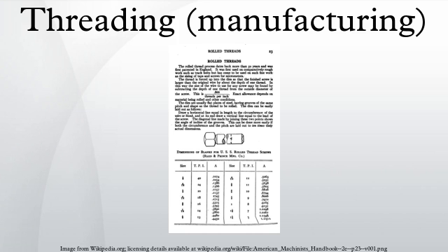Another variant of form milling involves holding the cutter's axis orthogonally and feeding the cutter in a toolpath that will generate the thread. The part is usually a stationary workpiece, such as a boss on a valve body or a hole in a plate or block. This type of thread milling uses essentially the same concept as contouring with an end mill or ball-nose mill, but the cutter and toolpath are arranged specifically to define the contour of a thread. The toolpath is achieved either using helical interpolation or a simulation of it using extremely small increments of 3-axis linear interpolation. The cutter geometry reflects the thread pitch but not its lead. The lead is determined by the toolpath.